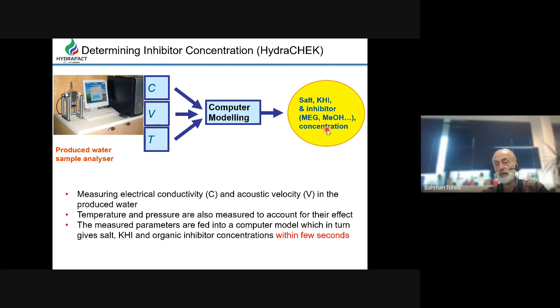So for some places where we have basically a buffer solution, we can use the buffer solution as another unknown. So basically we tune the model based on 15 to 25 Celsius. And from there, within 5 seconds, we determine the amount of inhibitor. Just real time. Then you can make a decision. No chemical, nothing. You just press a button.